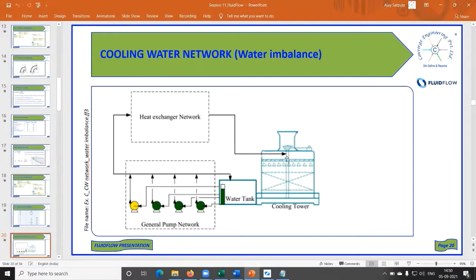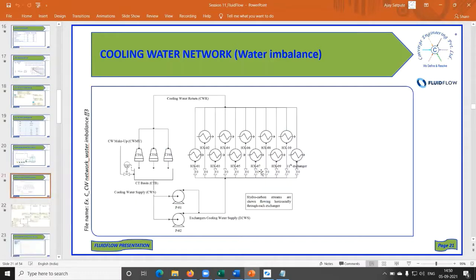Some water will get evaporated, and the heat will be taken up for the evaporation, and the water in turn will get cooled. The moist air will go out of the cooling tower because of the fan. And the water, when it drops down, will be at say 30 degrees, so accordingly the cooling tower vendor will design it. Again, the 30 degrees C water will be sent to the cooling water supply pumps, and the same cycle will get repeated. So there is another picture of this.